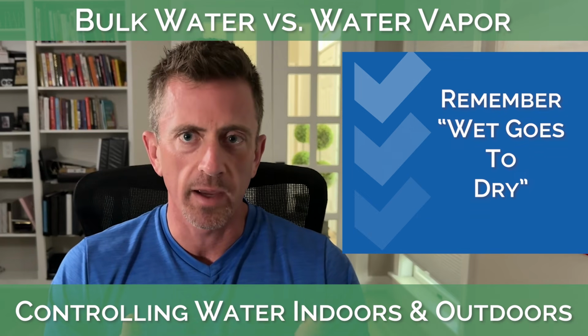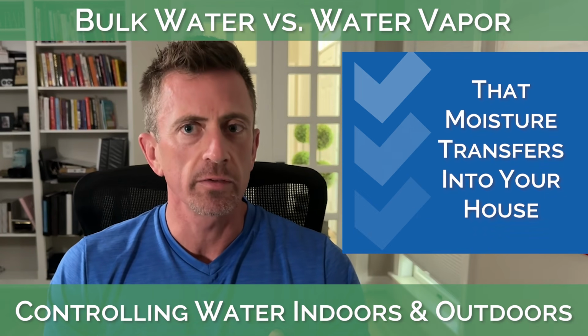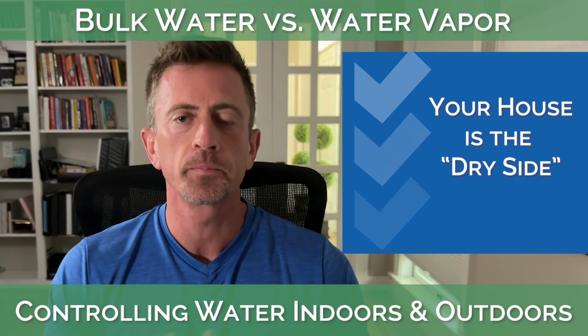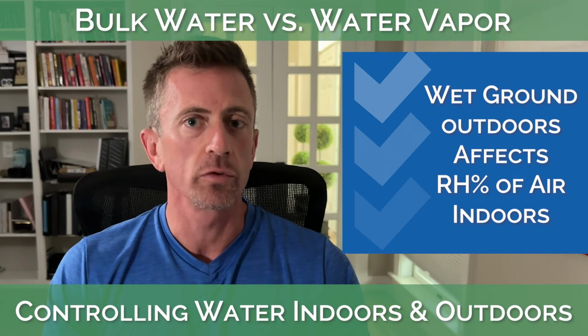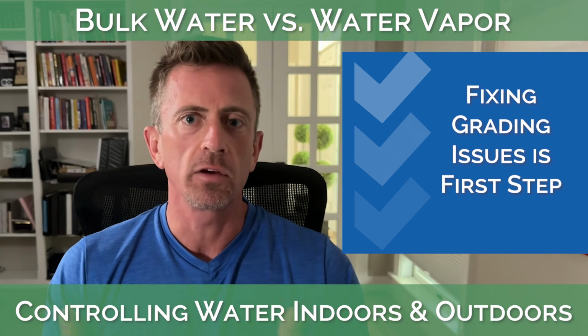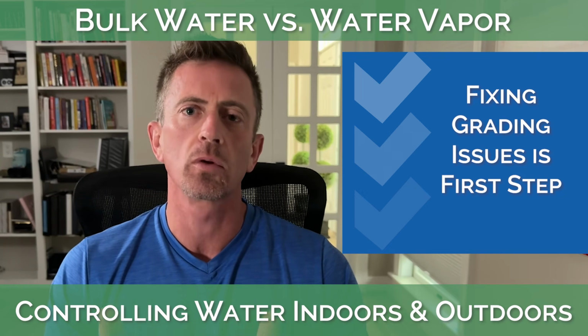Remember, wet goes to dry, and moisture eventually transfers into your basement, cellar, or crawl space, which is the dry side. That wet ground outdoors really can affect the relative humidity of the air inside your home. Fixing any grading issues is the first step in fixing bulk water problems.